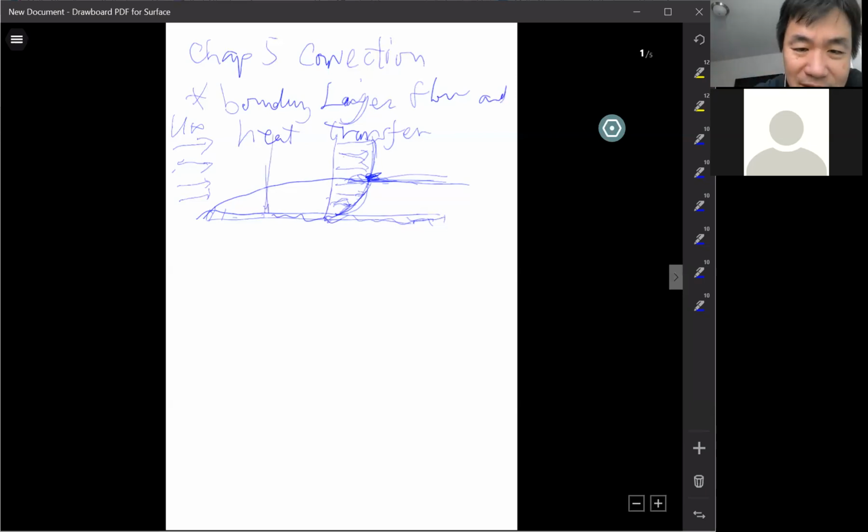So it seems like the boundary layer thickness is going to increase when the flow goes further down the plate. At the beginning, the velocity defect area is smaller. Bear with my drawing, but do you understand what I'm talking about here? The defect region, the velocity reduced region near the wall, gradually increases.